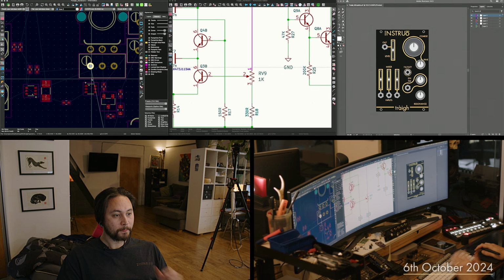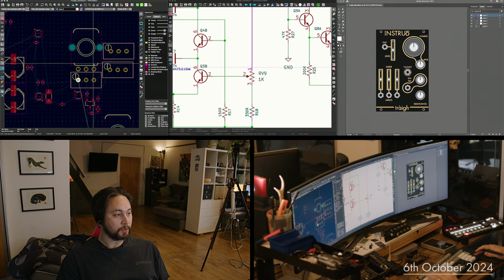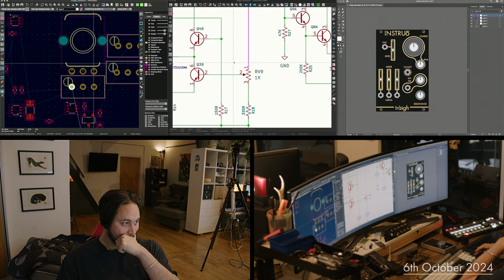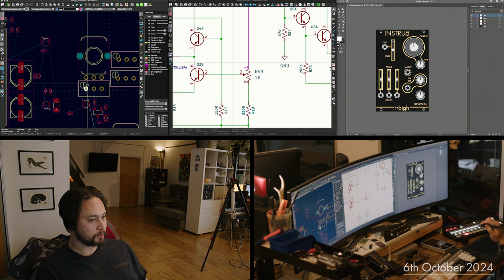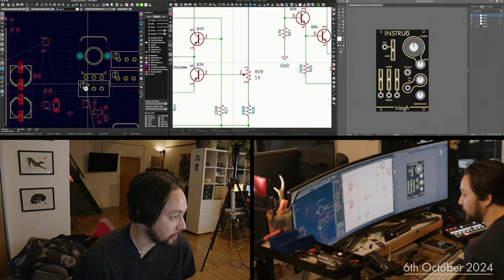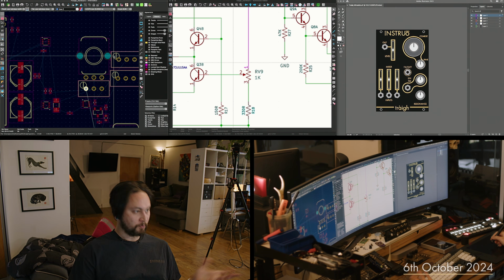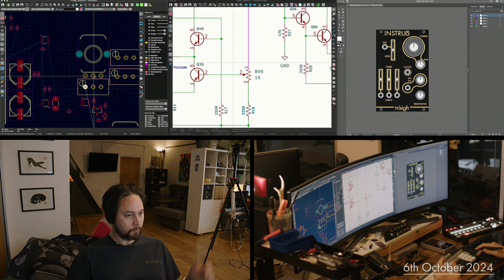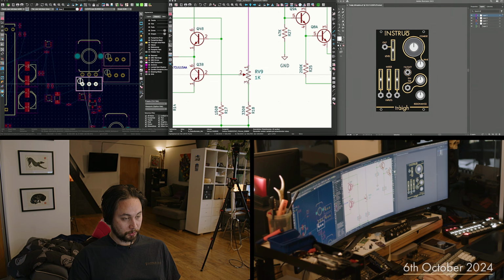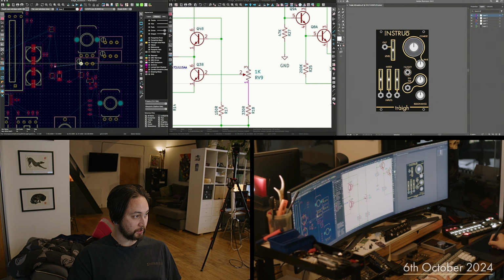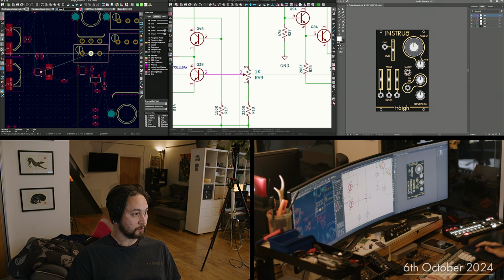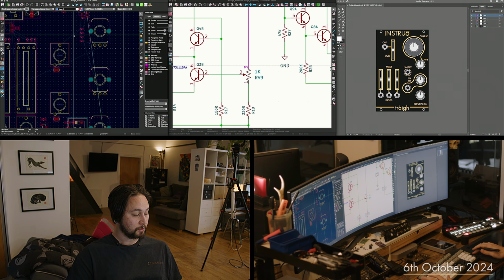What is that? That's feedback, right? Okay, so what I might actually do in that case is, doesn't matter which direction that trim pot turns, it's manually calibrated with the trim pot anyway. So it doesn't really matter whether it's clockwise or counterclockwise. It's just whatever way it is. So I'm going to flip these pins, because it'll still function the same, but that's giving me neater directions for these,